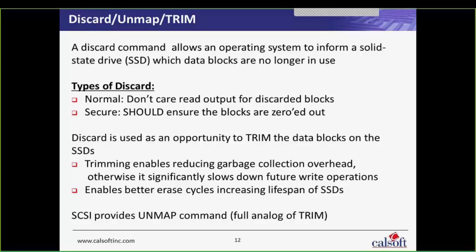Otherwise, it significantly slows down future write operations, because the garbage collection engine will kick in and try its own logic to free up the blocks. The second thing is it enables better array cycles, increasing the lifespan of SSDs. It helps in doing the wear leveling for the SSDs. The SCSI command set normally provides the unmap command, which is a full analog of trim.